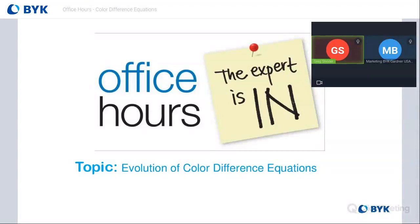If you don't have a multi-angle color measurement, you should probably use a sphere instrument, because that's going to basically illuminate from all different angles, and it'll give you one number. But depending upon how that bronze travels, if you can't use a multi-angle device, then use a sphere device.